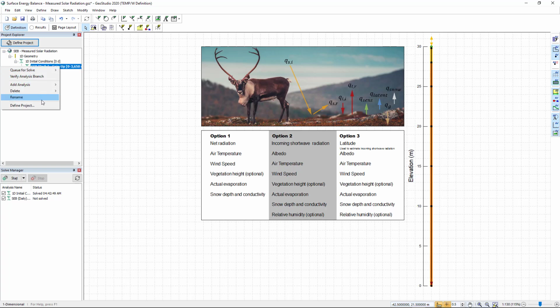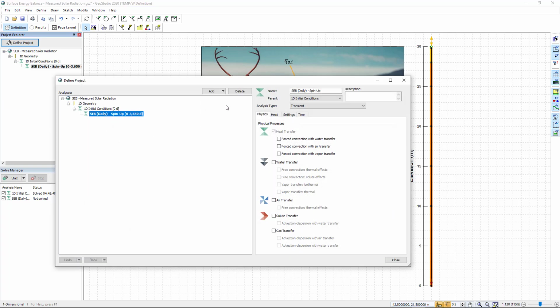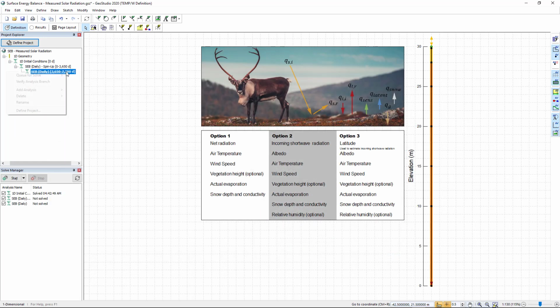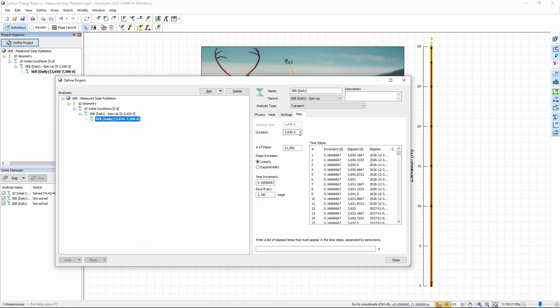So we go into the define project, and we're essentially going to add a new temp analysis. Temp analysis will be SEB daily. So that will not be our spin up analysis. And I'm going to close that. Yeah. So we're going to define the time steps here. So that will be over 365 days. And what we want to do is run that for every 4 hours.